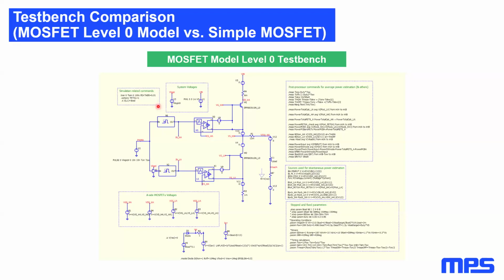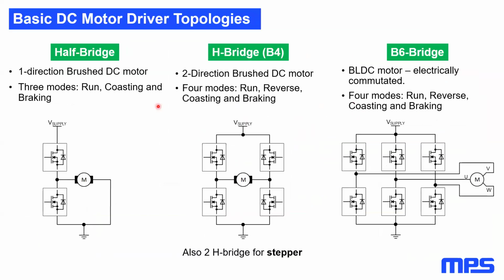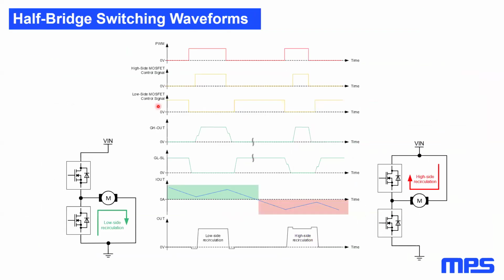Okay, thanks a lot. Next one is, in H-bridge, high side recirculation or low side recirculation, which is preferred? Oh, I don't think there is really any preference. I think at the end of the day, what may dictate a choice for a system level integrator are actually the capabilities of the motor driver that he is working with.